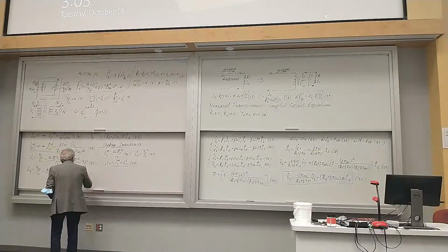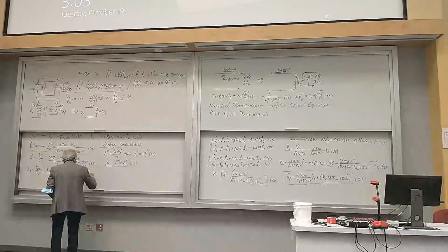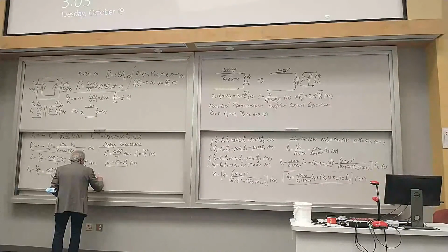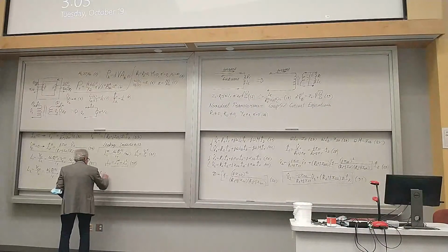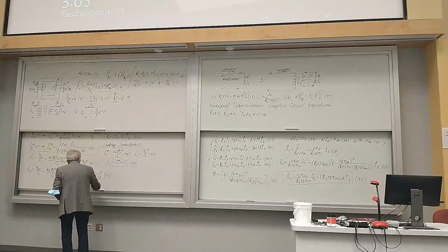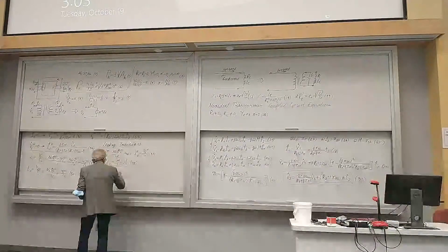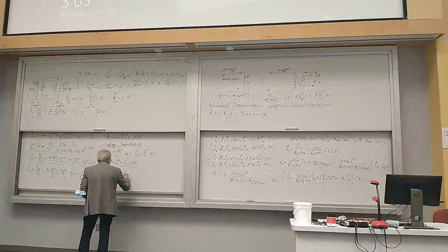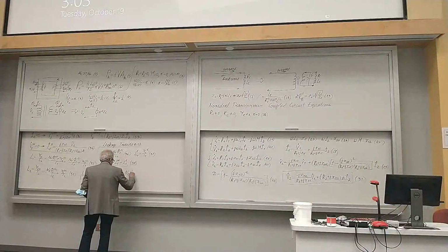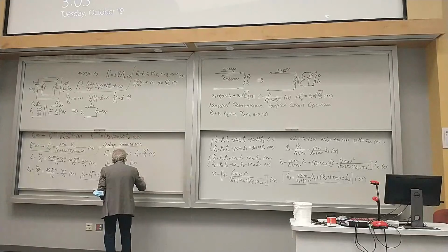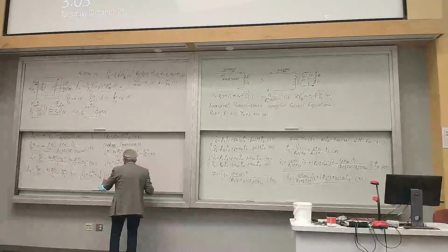And again, now you can write that L sub 2 has two distinct components. One is a main inductance, and another is a leakage inductance. The main inductance is the first term, and the leakage inductance is the second term in formula 39.